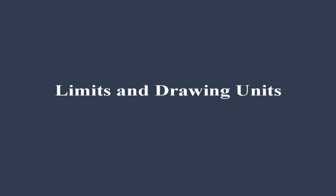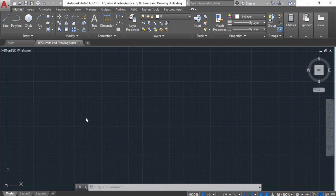Welcome to the next topic of our video, which is limit and drawing units. So now here we have a completely blank drawing area. In this current drawing, we don't know the extent of the drawing or its dimensions. For example, if you want to make a line of 10 units in this area, we do not know how long it will be. In order to set that limit, we can use the limits command.